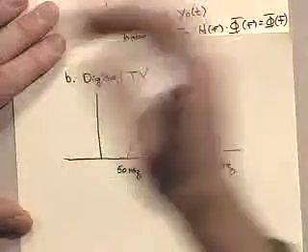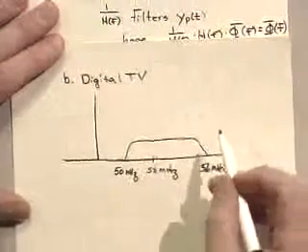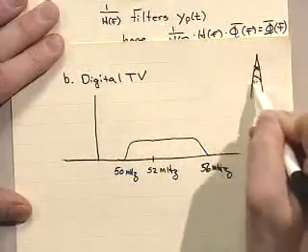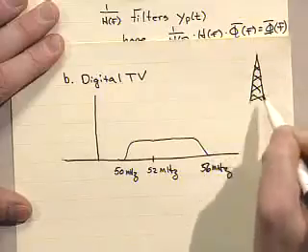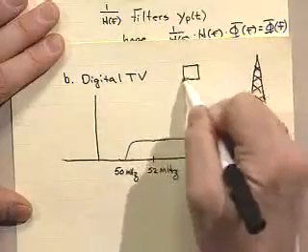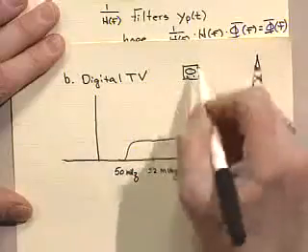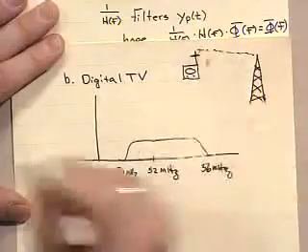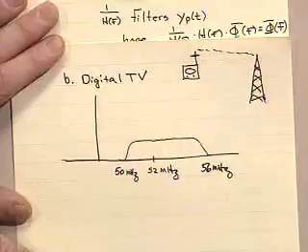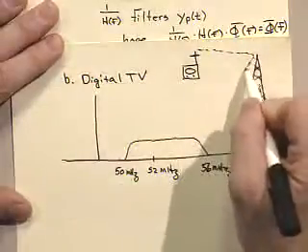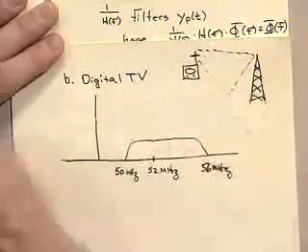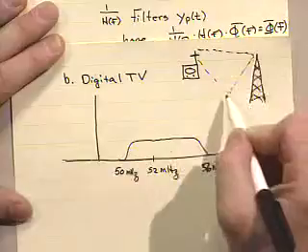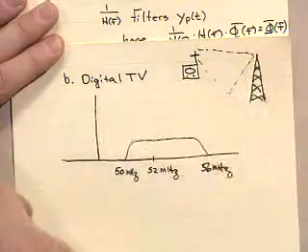But we would normally think wireless channel, what's causing any kind of filtering? Well, the issue is that the path between that TV antenna, somewhere up on top of a mountain, and your TV somewhere else. If there's a straight path here, you will have essentially a flat channel. But if that signal bounces anywhere else, off the ground, off a mountain, off some metallic object, then there are two paths. And the delays on the two paths may be different.